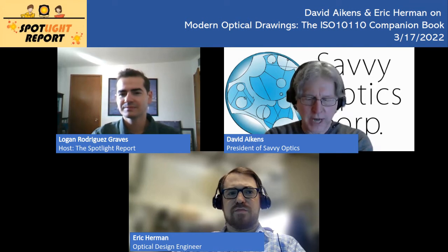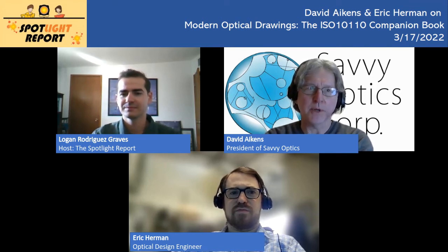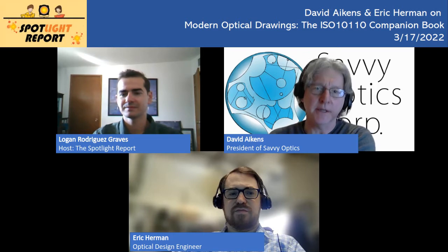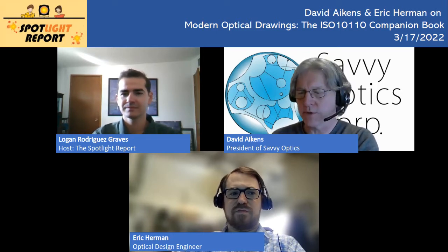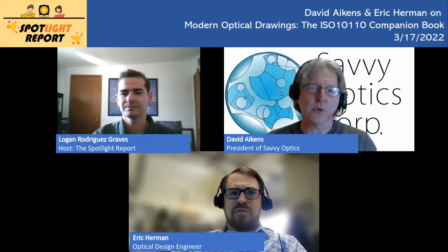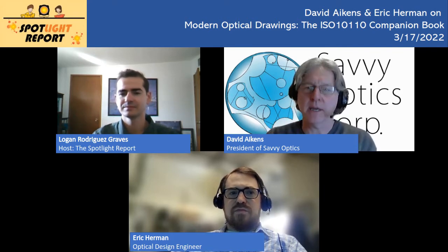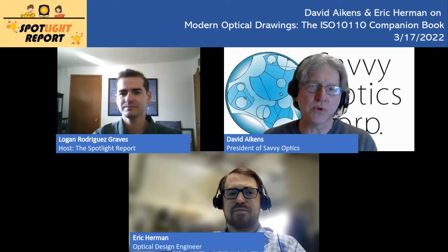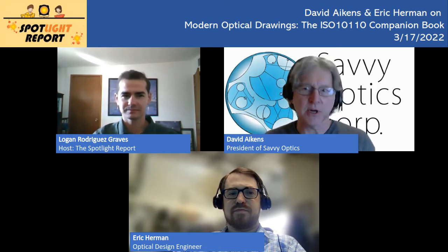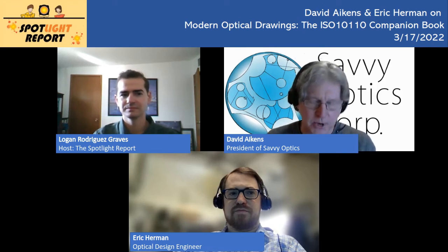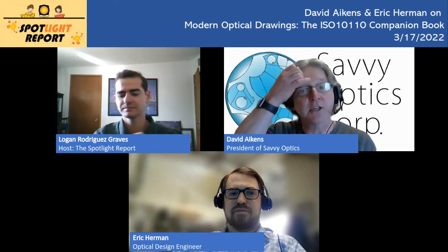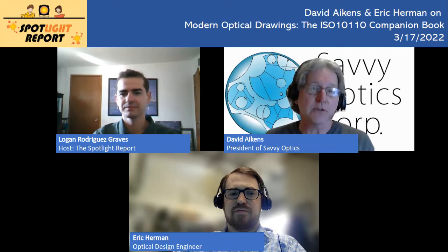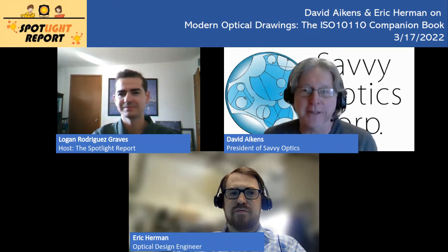Yeah, well, chapter 1 really draws from what used to be parts 1 and 10 in the ISO 10110 system, which was assuming you're starting from ISO 1101, so you're making a mechanical drawing. What special rules do there need to be for optical components and optical tolerancing? One of the most obvious to any mechanical engineer is when you get an ISO 10110 optics drawing, most of the time there is only a single view, and any mechanical engineer can tell you you can't do that. That's not allowed in GD&T.